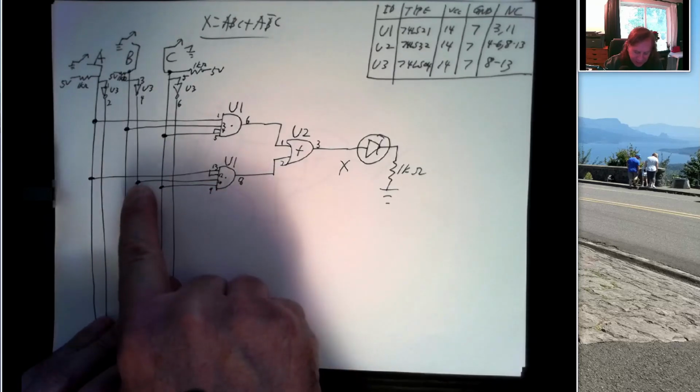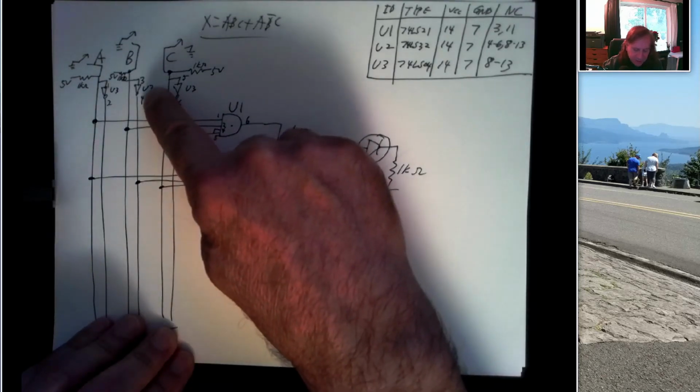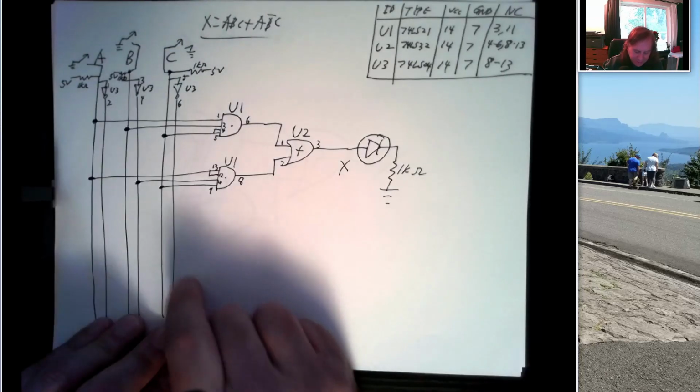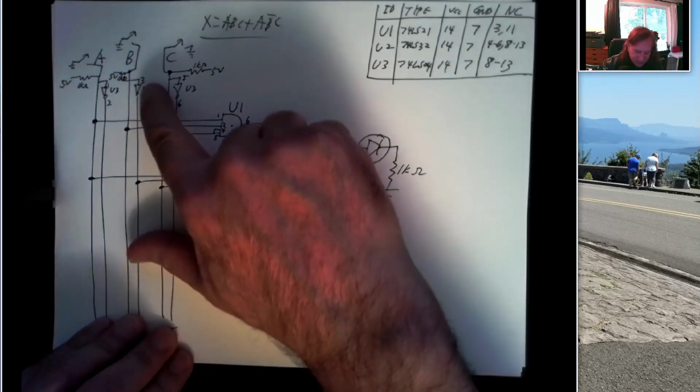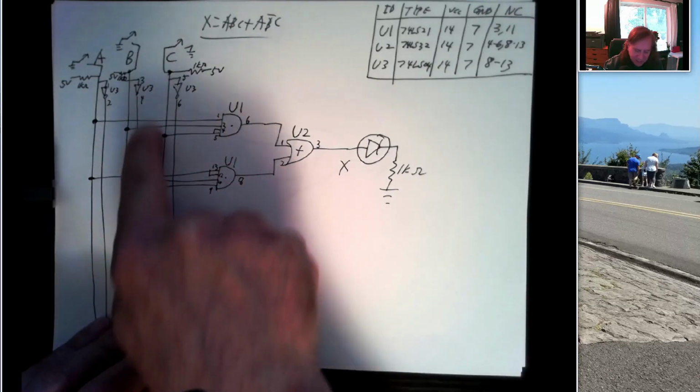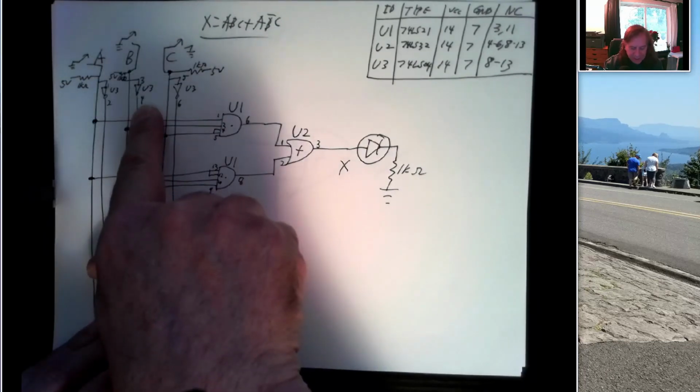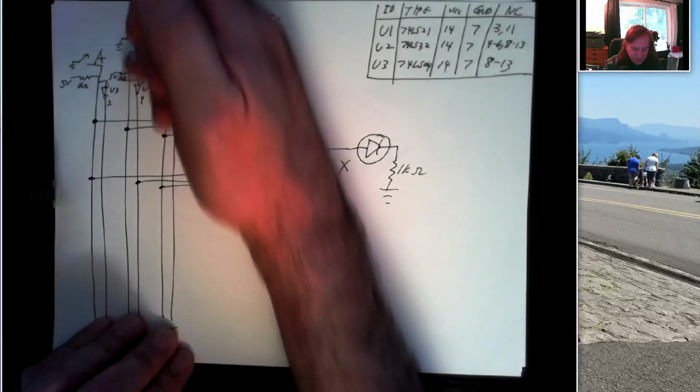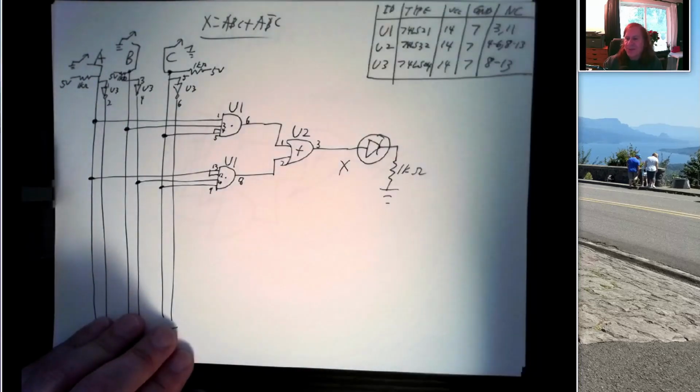Well, where does pin 10 come from? It comes from pin 4 on U3. So take a voltage reading there. If we expect this to be 1 and it is 1, and it's a 0 down here, there's a problem with that connection. If this is a 0, then there's a problem somewhere here. And we can keep tracing our circuit back.